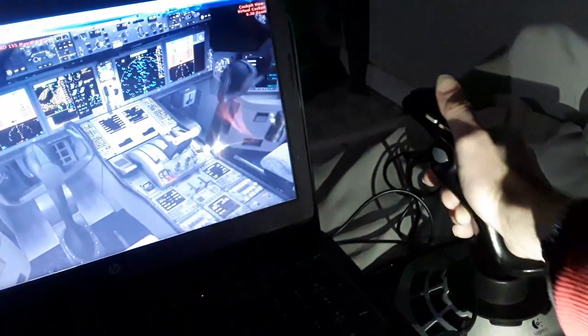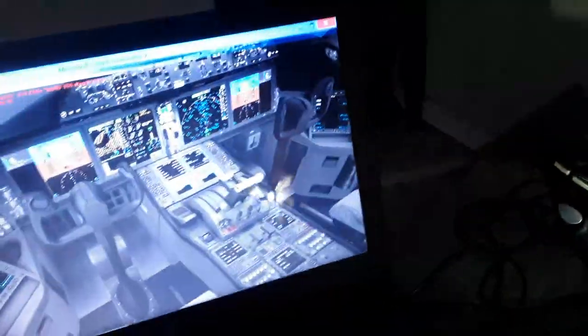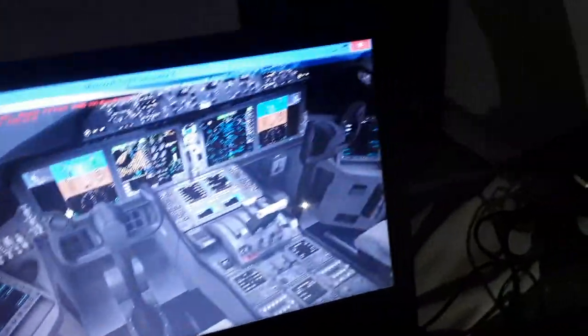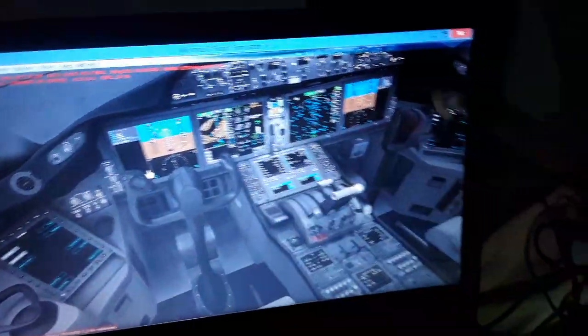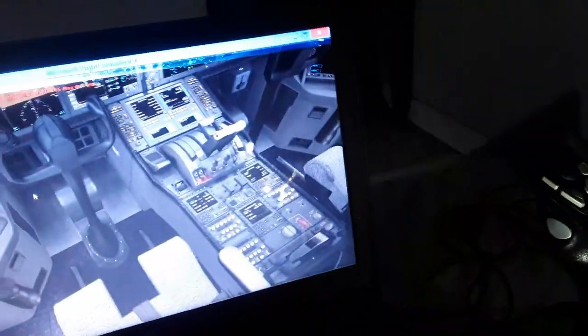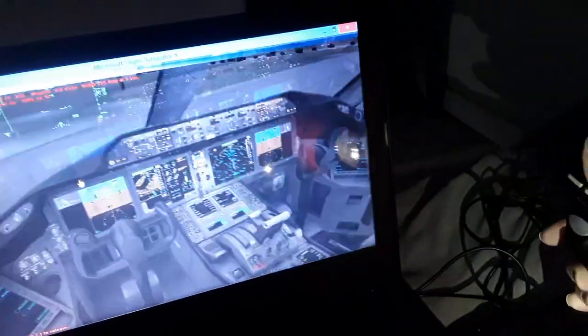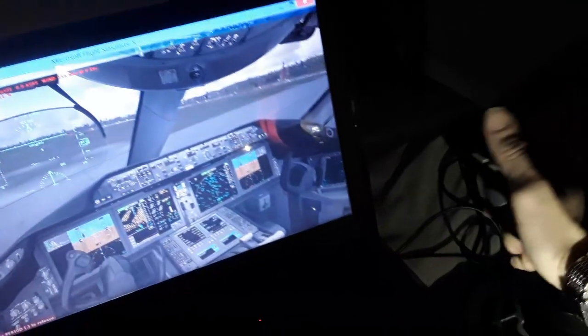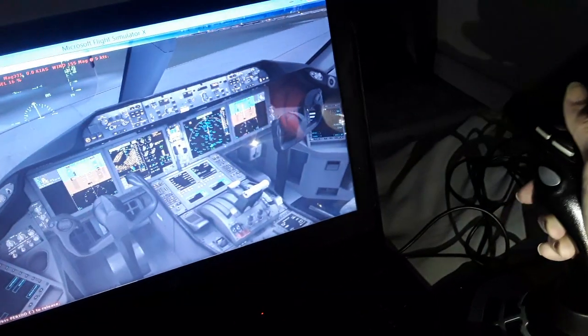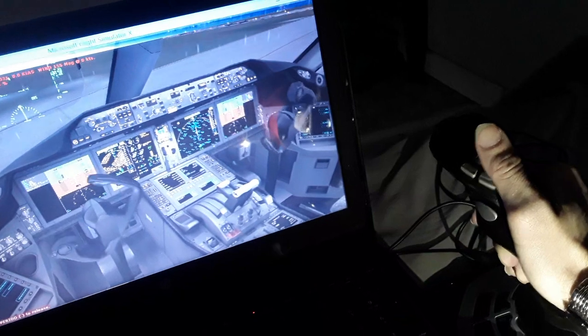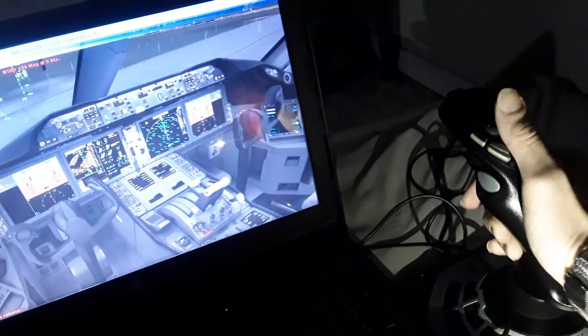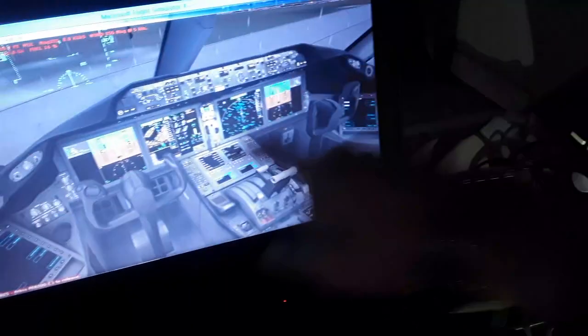So you can see the flight controls movement. So that was the explanation of the aerodynamics of the aircraft when we fly, in Newton's physics. So we need to know a few more things. The flight controls. I told you about the horizontal trim stabilizer, what to do with that. We have the effect from the elevator, as you see, climb and descent, the pitch axis. We have the lateral, the longitudinal axis for making turns left and right, and also the rudder pedals, the vertical axis.